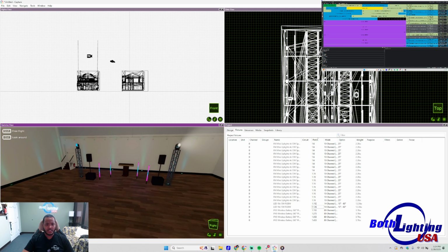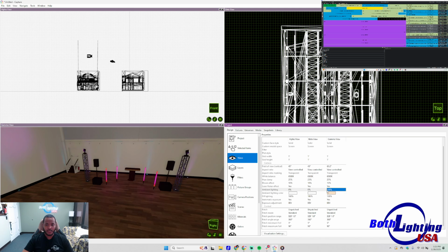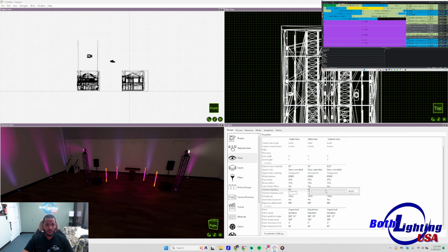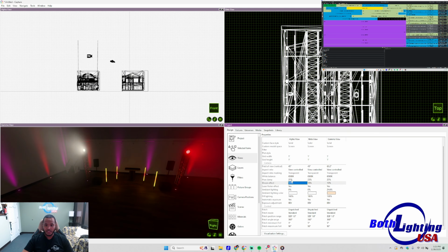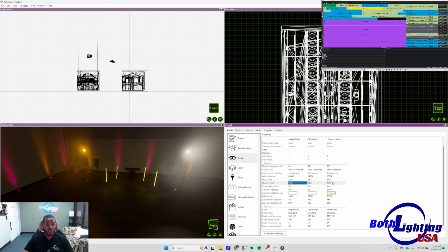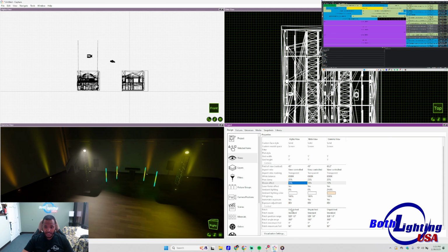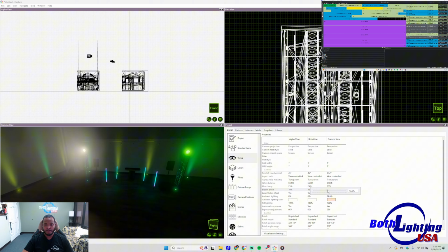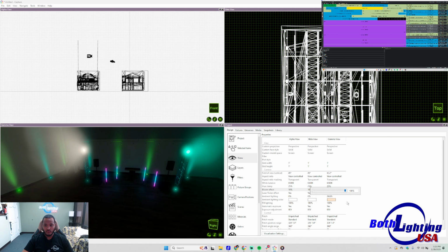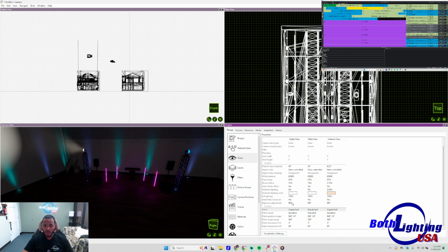programming. So as you can tell, the room is still super bright, and we want to kind of see how that looks. So we're going to go back to that ambient lighting and turn the ambient lighting down, so we can see realistically how that room will look when it's time to party. And you can adjust the bloom, which will show the rays, and also adjust the atmospheric haze. So you can see the bloom there. We're going to turn that down to about 20%.